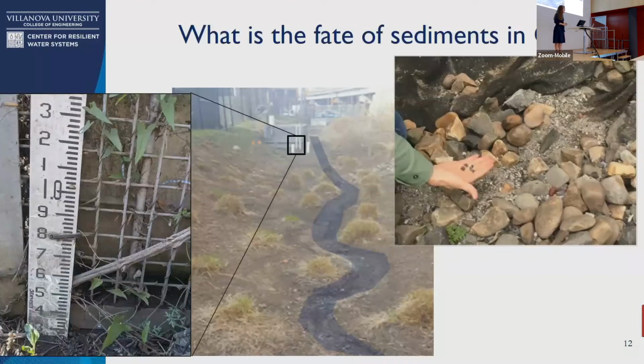And then we looked at the outlet of this, and we noticed that there had been a ruler put in to look at how much sediment was being deposited. And this is roughly 3.5 inches. That translates to about 7 centimeters of deposition that happened in just 3 years of this baby rain garden's life. So just in the first 3 years, it got 7 centimeters of deposition.